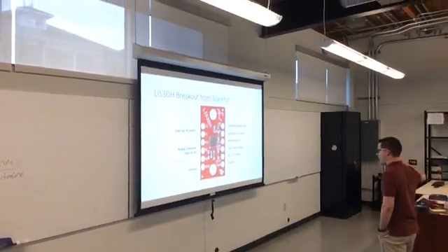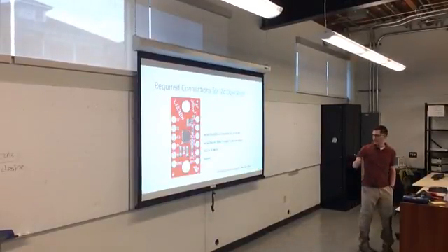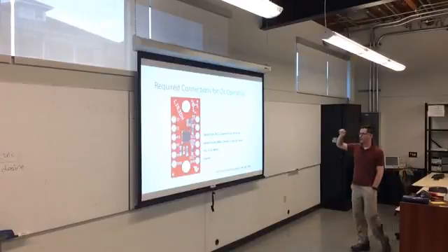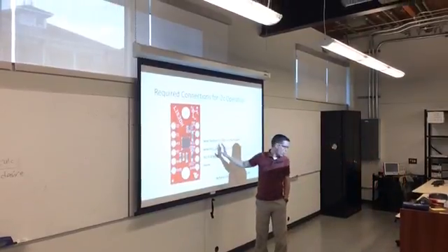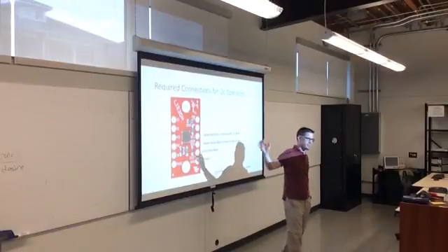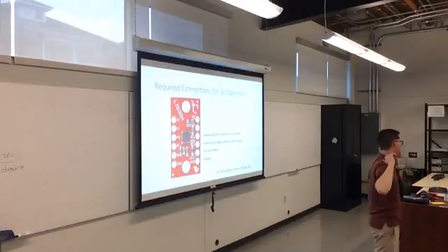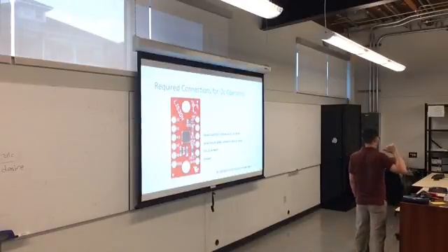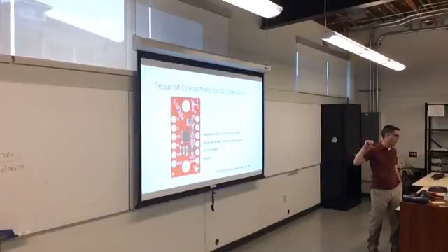And one benefit of this device is that they've already built in the pull-up resistors that are needed for the I2C interface. So you don't need to go to the back and fish out some resistors and use a breadboard. You can directly tie your pins to your processor. They've thought about this with this board. They've done some things to help you.